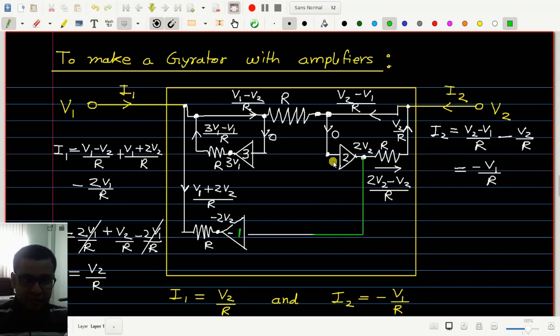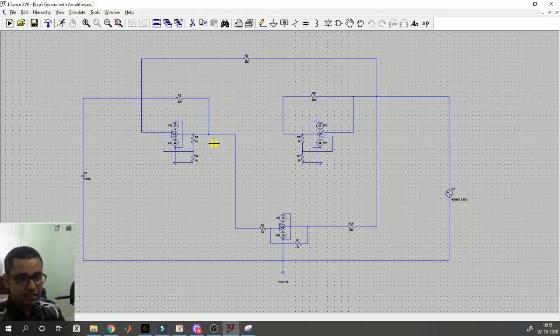Okay, so already voltage is doubled here, and then you multiply with -1, so effectively we will get an amplification with a factor of -2, and then no current will be drawn from here. Okay, this amplifier can draw current, but that will come from the output of this amplifier. That is not a problem, as long as no current is drawn from here. Okay, this is the circuit.